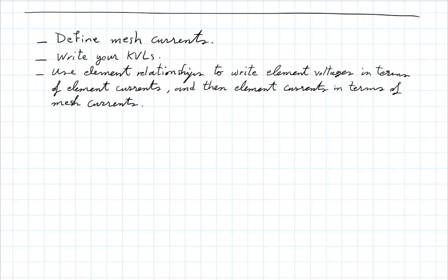But that's fine because the information that the current source provides, namely its current, then gives you also an additional equation. So very similar to what we saw in nodal analysis, but there it was voltage sources that created this little bump. Here it's current sources that create this little bump. But they also provide additional information, hence additional equations, and there's no problem.